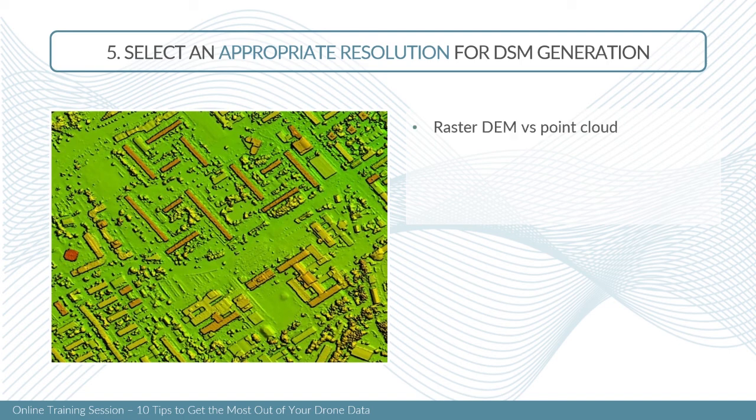First, let's just talk a little bit about the difference between a raster DEM and a point cloud, because that's two different things. In Correlator3D, by default, we're working with raster DEM. That's a regular grid, a matrix of elevation that will be in the format of a geotiff. And that's what the software uses if you want to do edition or when you generate a terrain model out of the surface model. The software uses this format to work with.